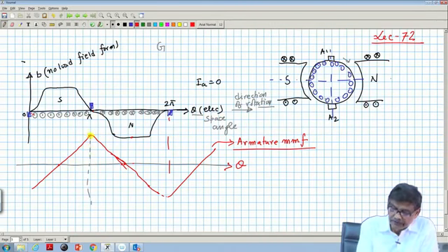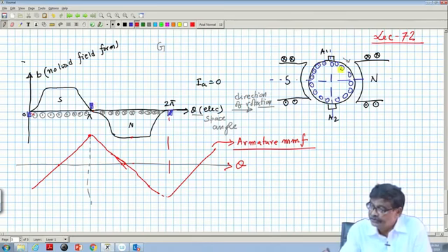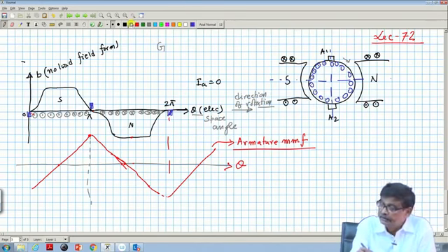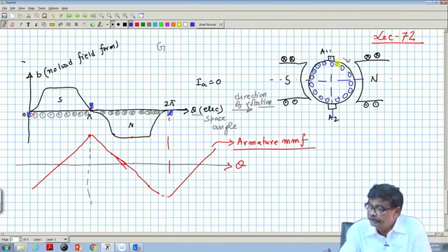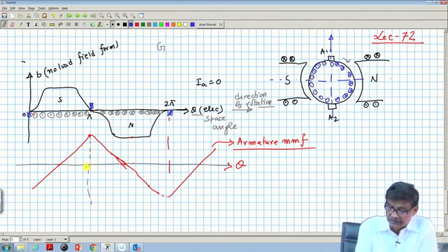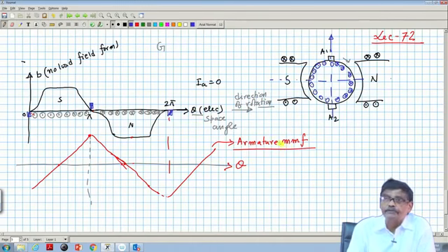So this is the peak value of the armature MMF, along the brushes, consistent with this current distribution, cross, cross, cross, cross, cross, cross, cross. This is one armature terminal. So the armature MMF will be here, and that is also depicted here, the peak value. But this is MMF, not the flux density.